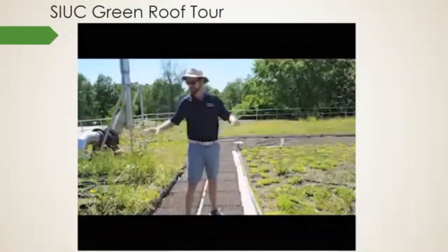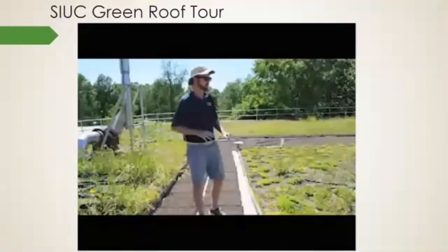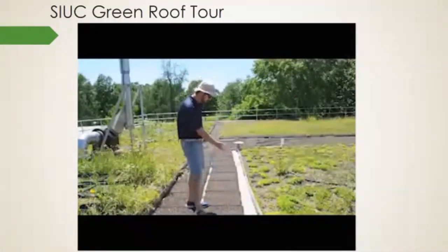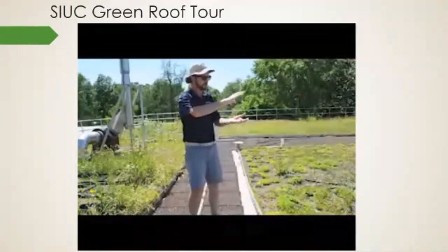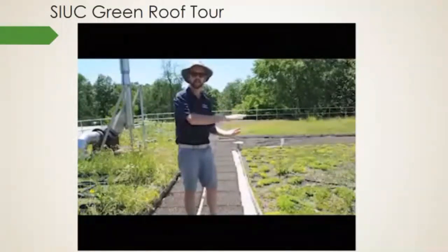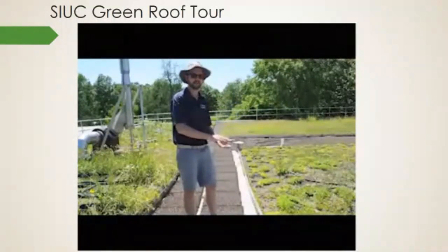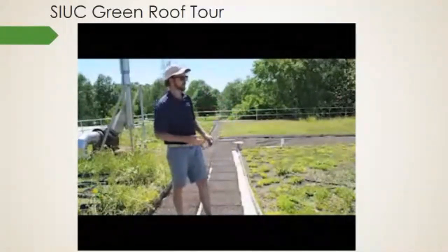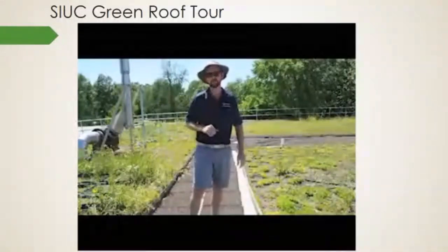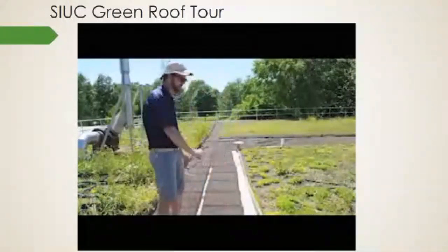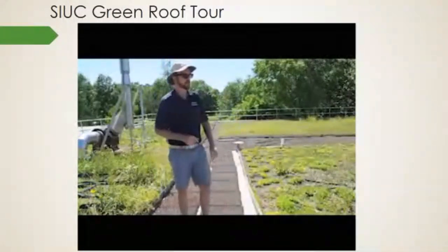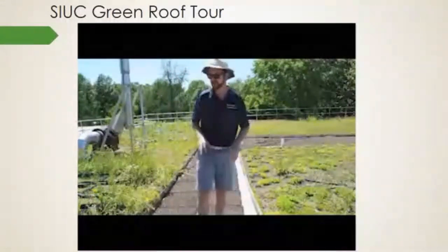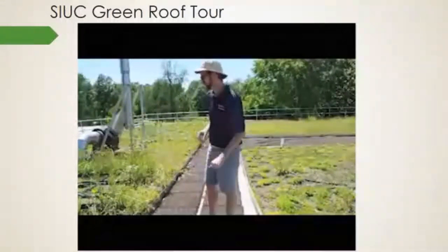But we have a few different sections up here on our extensive green roof that was installed in 2010. You can see this aluminum edging here, and that's holding in the layered system, the layered medium with vegetation on top, drainage layers underneath, and this is all bordered in these sections by our aluminum edging. Then we have these nice permeable pavers up here, and that's all over the top of the impermeable vulcanized rooftop membrane here that's waterproof.